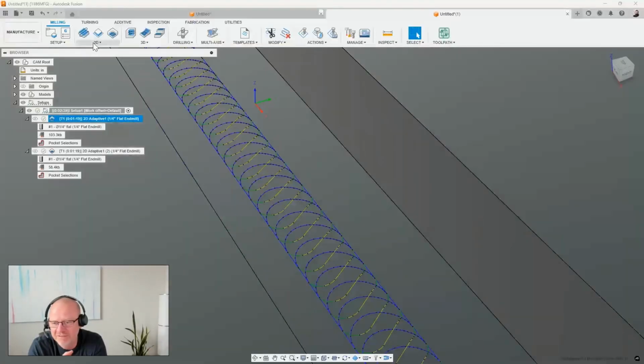Yeah, adaptive doesn't do well on narrow walls, where the spacing is just slightly bigger than the tool diameter. Like you've got a 10 millimeter slot with a 6.35 millimeter cutter, then there's not a whole lot of wiggle room. And like Devin highlighted, the stock to leave also accounts. So when I come across features like that, I find that just doing a slotted toolpath, even like you said, a ramp slot down, would be a quicker cycle time in that area. But maybe Devin can show it, see which one's faster.